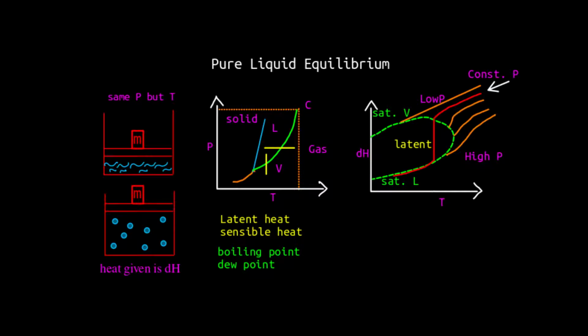First, let us plot the composition, that is vapor liquid equilibrium curve, which can be plotted as mole fraction or moles versus temperature or partial pressure or total pressure versus temperature. So assuming that we have started with the liquid state, as we provide heat, the temperature increases and bubble point is reached. That is, the water vapor starts to form. At this stage, there is no change in temperature, but the phase change occurs until all water evaporates into water vapor. Only then, the temperature of the vapor phase increases if we continue supplying heat.